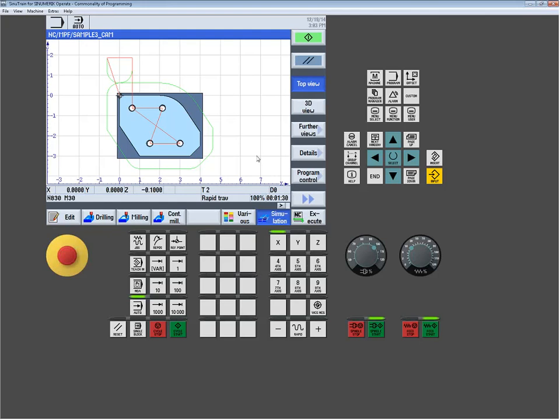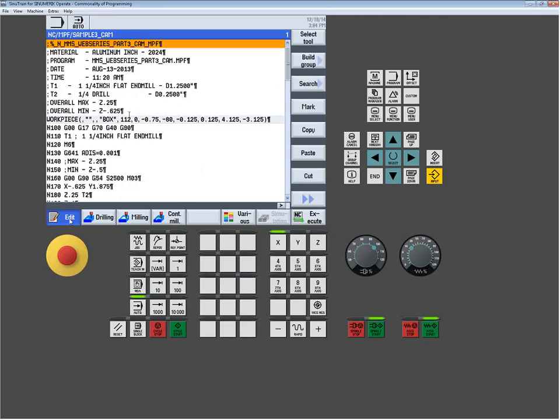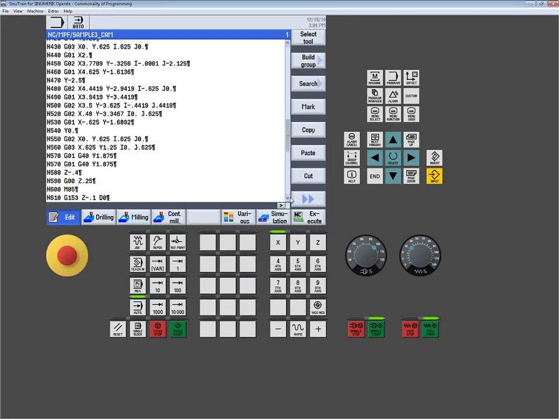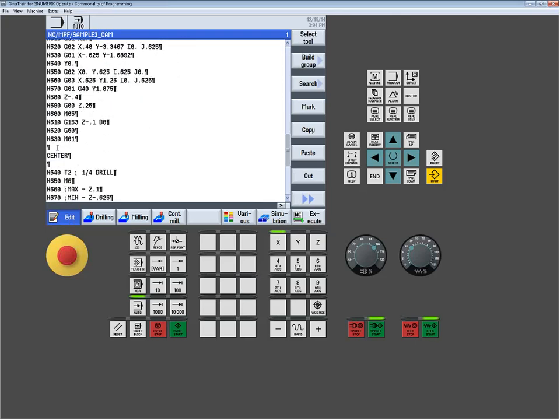So certainly the mechanism of using really anything as a subprogram can really allow you to add functionality, modify functionality, even on elaborate posted programs, pretty quick and easy. And again, remember that entire example could have been 100% a conversational routine as opposed to G-code. So even if you're a guy that's using the machine conversationally, but every now and then gets G-code programs fed in, you can add the same kind of functionality. So it's as simple as just giving it the name of the file right there, center.